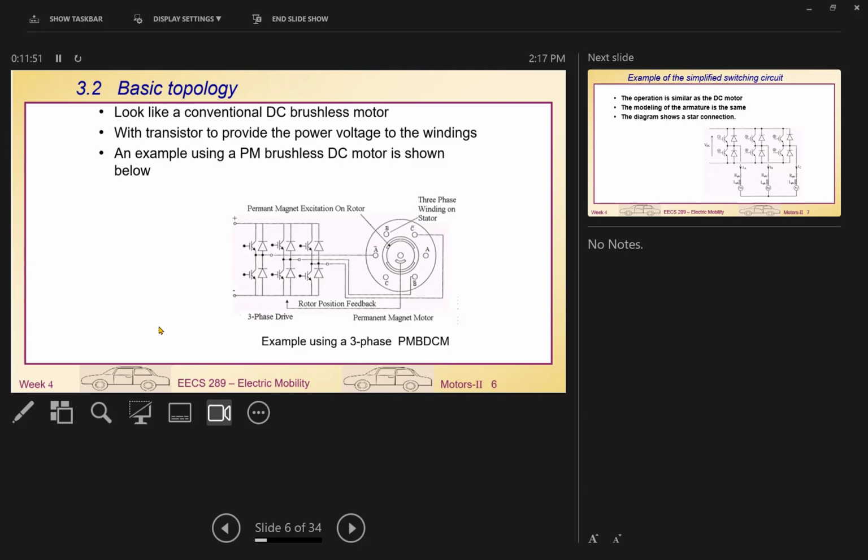So the motor will be in here. We got 3 sets of the winding. And then on the left-hand side, we got the motor drive. So this motor drive is different from an H bridge. We call it a full bridge or the 3-phase bridge. So we got 1, 2, 3, 3-phase to connect to the 3-phase winding here. So you can imagine the 3-phase winding more like this.